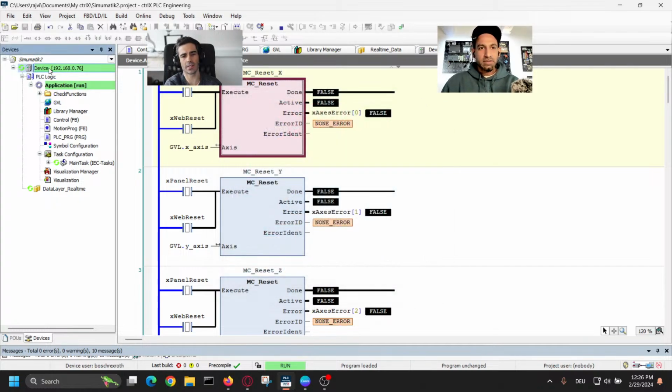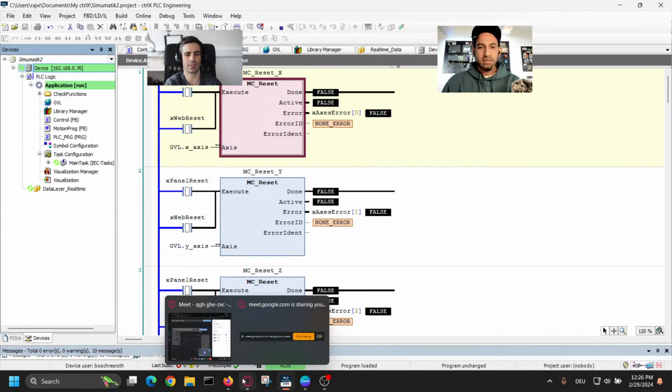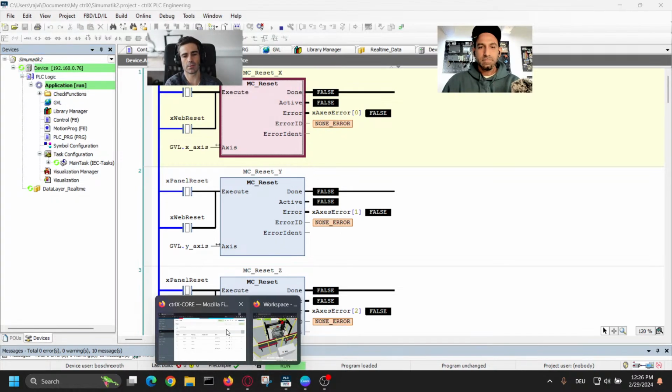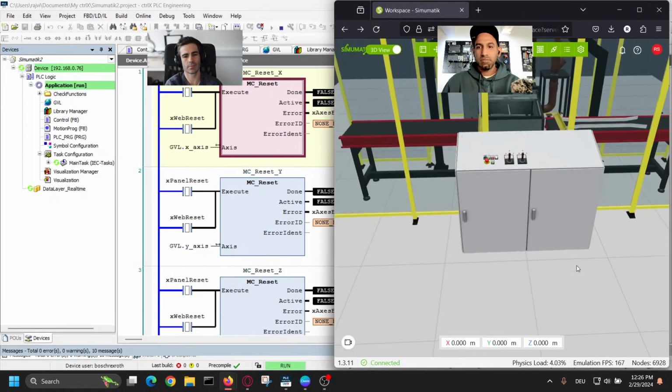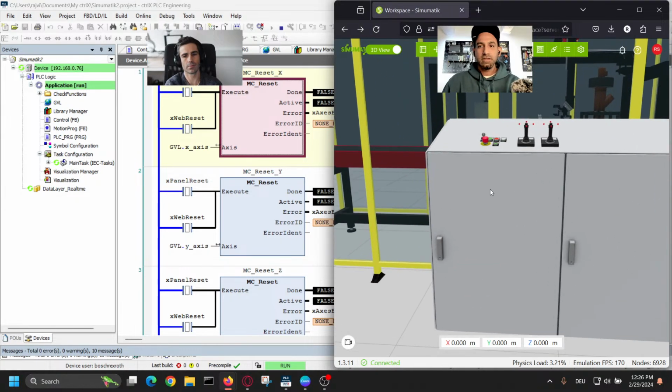So I have my... sorry, Rashbir, the connection in the generic PLC is also OPC UA, right? Yes, it's OPC UA, you use the same channel for drives and the IOs. Good. So for the connection here, I'm also using the generic PLC acting as an OPC UA client.